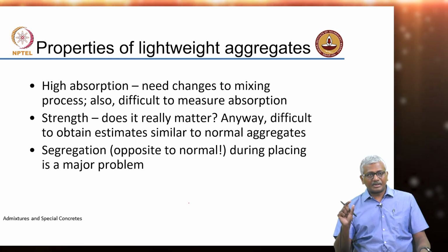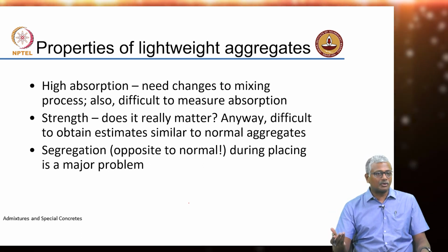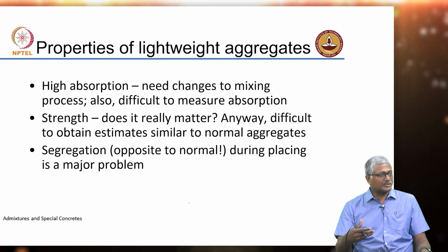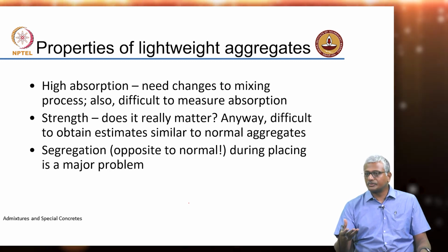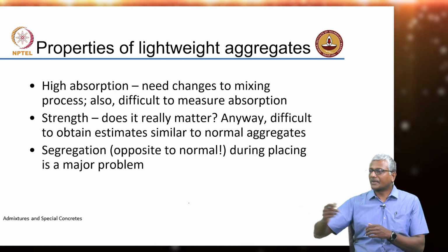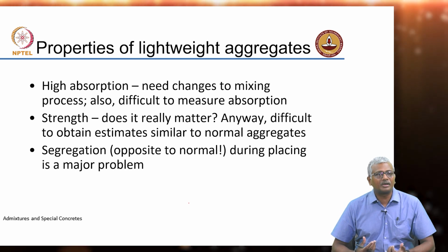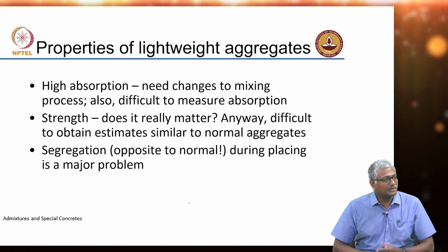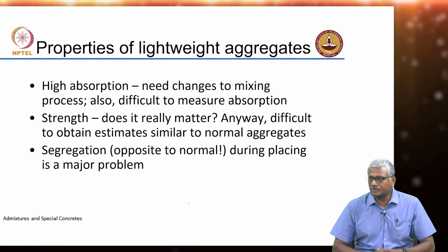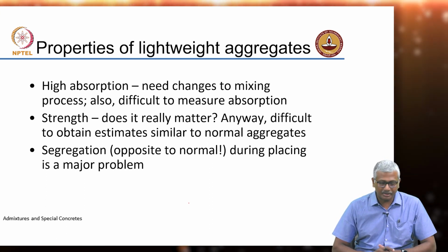But the crushing test or impact test that you do for normal aggregates, you cannot really do for lightweight easily, because unless your lightweight aggregate is of the type of sintered fly ash or expanded clay and all, which may have some strength in it, all other aggregates may just get crushed to powder when you do the impact test or crushing test. So, you need to adopt the tests carefully for lightweight aggregate.